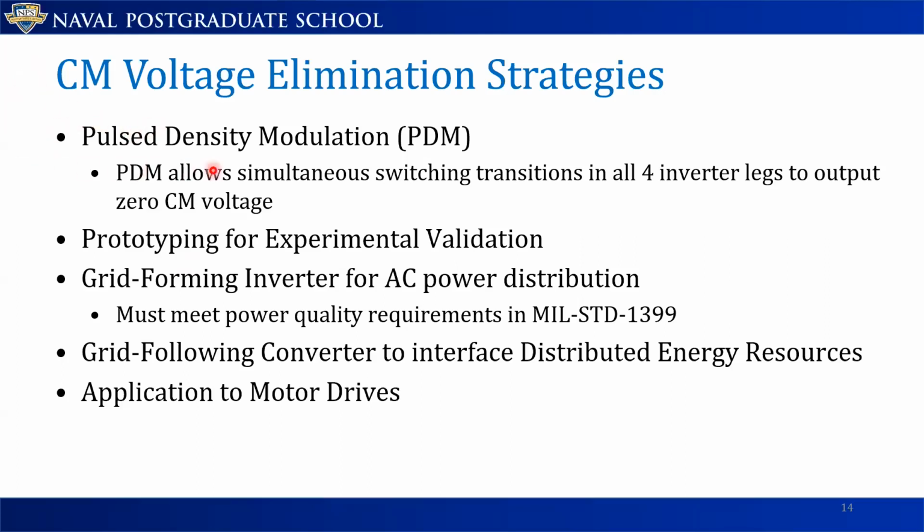I mentioned pulse density modulation. Our idea is a 4-leg inverter with pulse density modulation to cancel common mode voltage. Pulse density modulation, with respect to pulse width modulation, has the advantage that you can switch all 4 inverter legs at the same time.